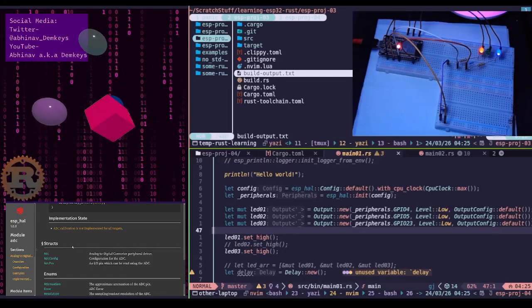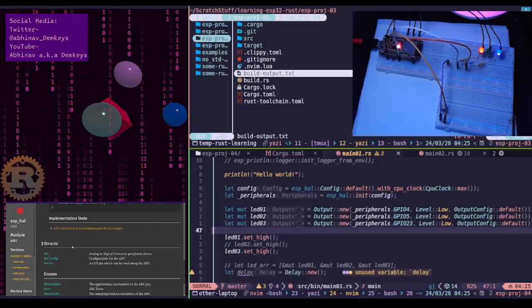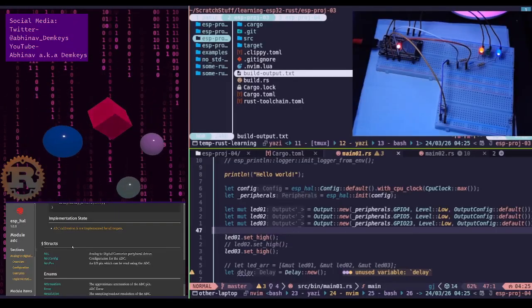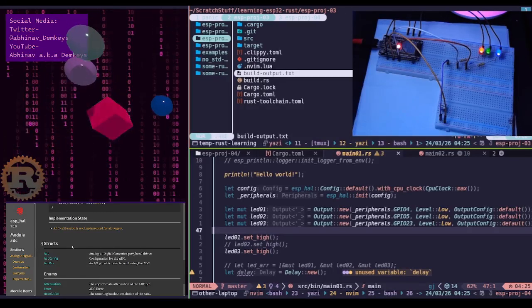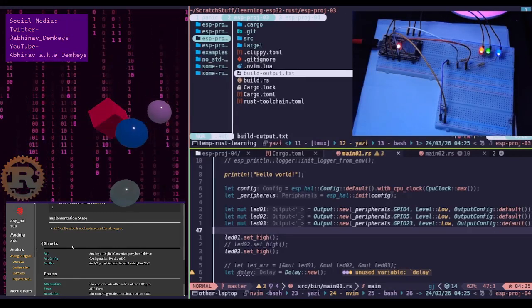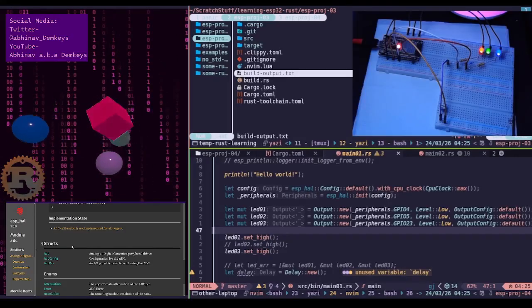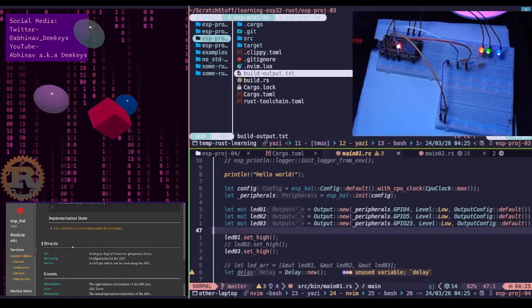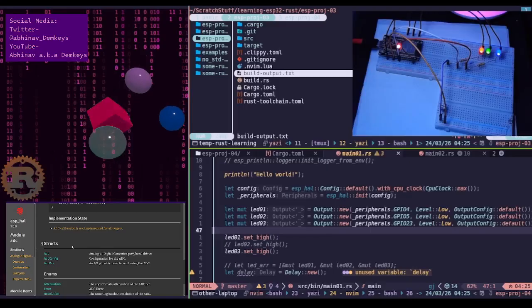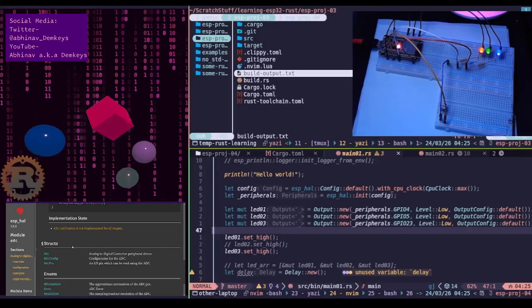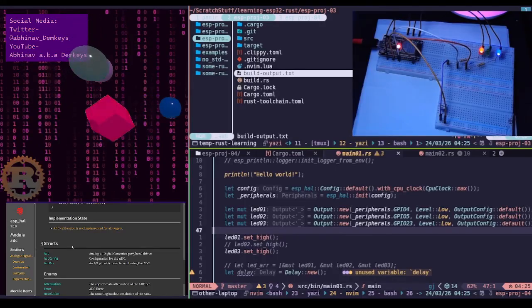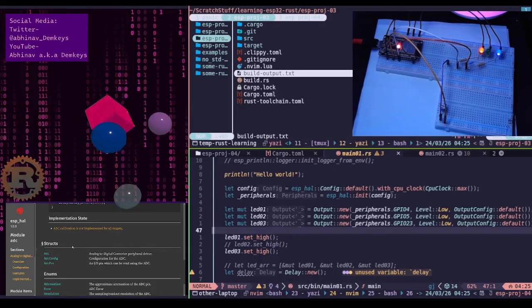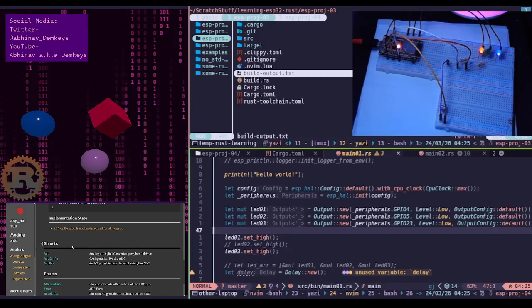Usually in a beginner setup, there are two ways to use this. Analog input: you use the pot to tell the ESP32 a value like a volume knob, then use the ESP32 to dim the LED using PWM. And another is current limiting. If you were using the pot directly with the LED, no ESP32 involved, the extra resistor is a safety net.